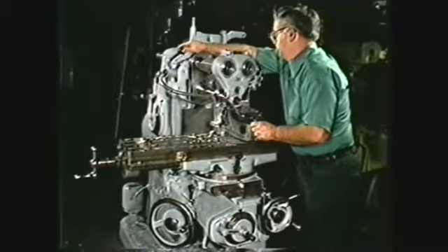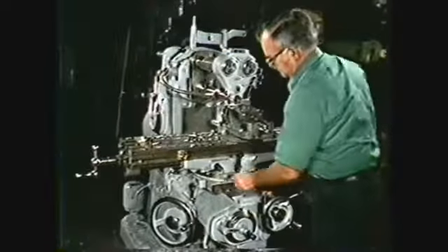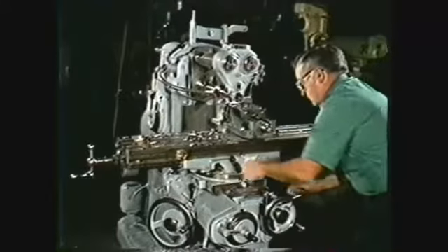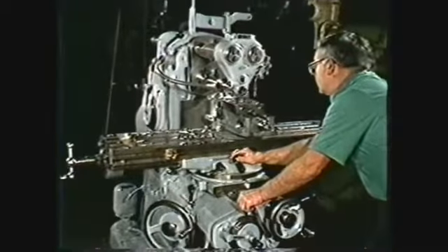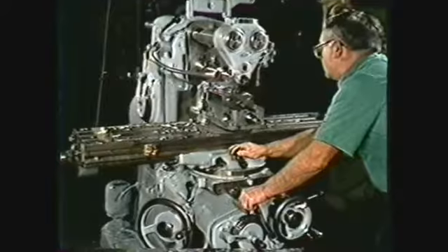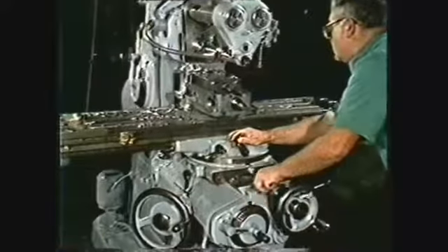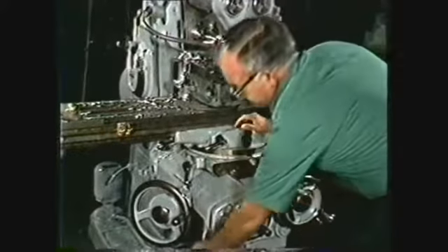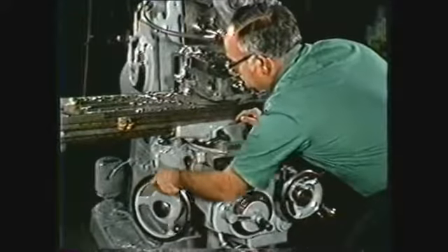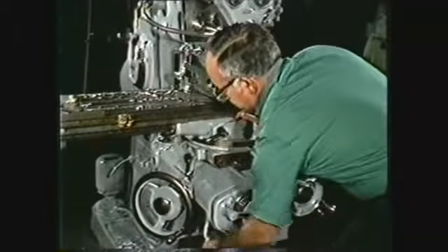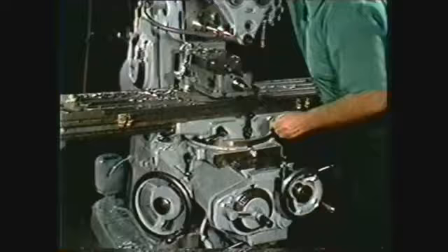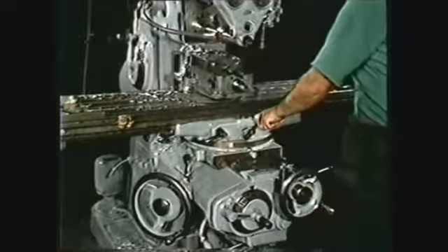When the roughing cut is completed, shut off the spindle and use the rapid traverse to move the table back to the starting position. Unlock the knee and move it up for a 20 thousandths finishing cut on the workpiece. Lock the knee and complete the finishing cut on that surface of the workpiece.